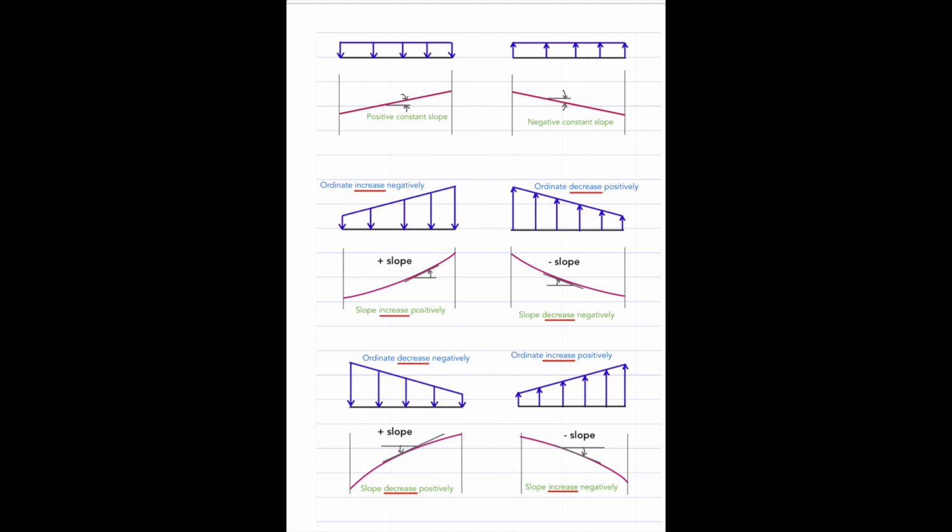If we consider a load diagram, then the shear force diagram should have a variation like this. Why? Because only if this line is a straight line and faces upwards, then the positive constant slope measured here can be related to this downward acting force.